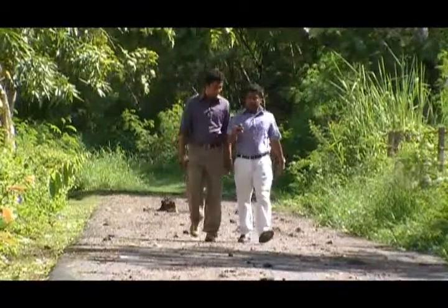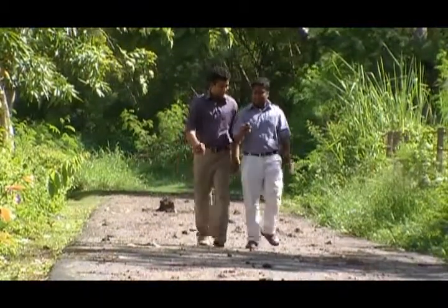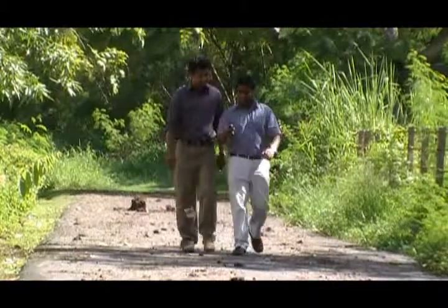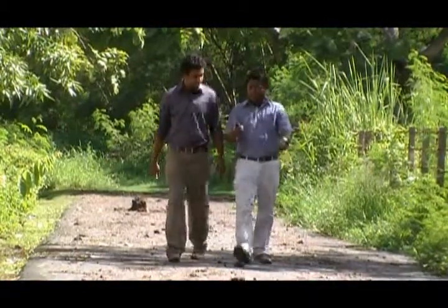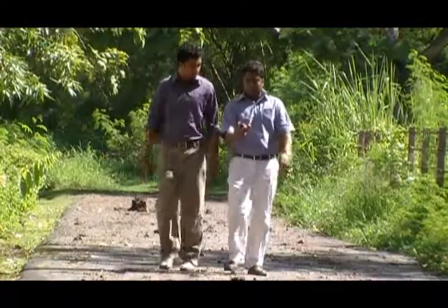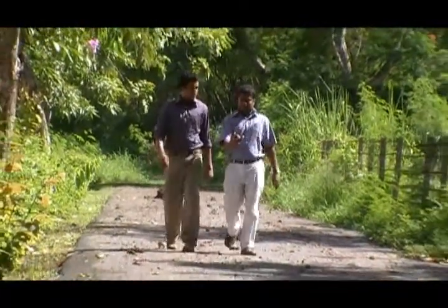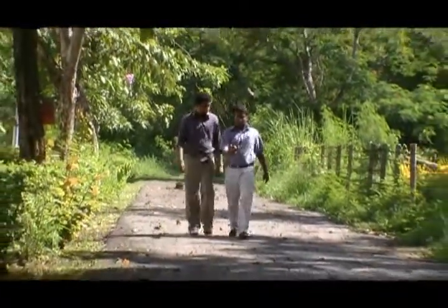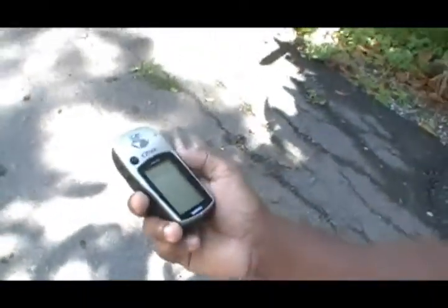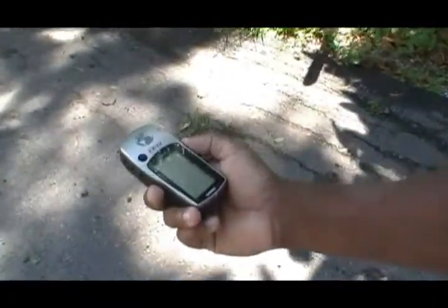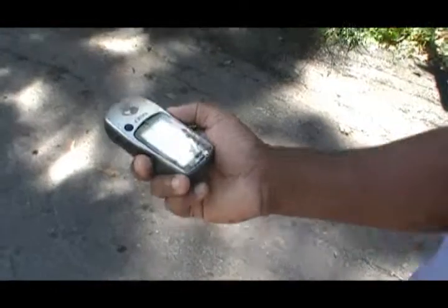When you enable the track recording feature, the GPS unit will automatically set track points as you go, essentially laying a breadcrumb trail to show where you've been. You can adjust track points to be laid at specified intervals of time or distance. The shorter the distance between track points, the more accurate the path back.